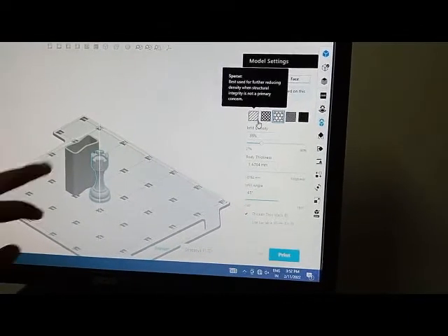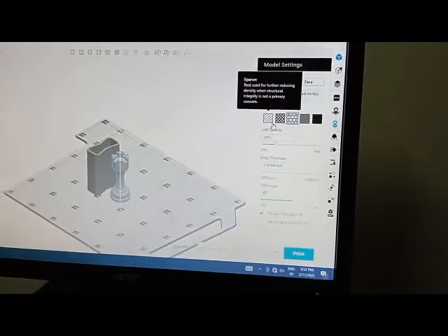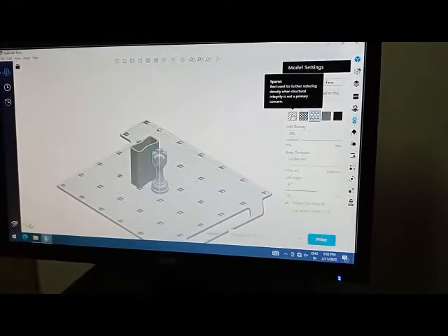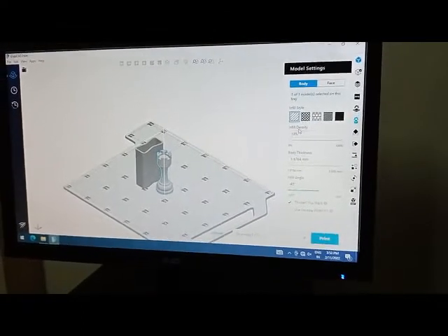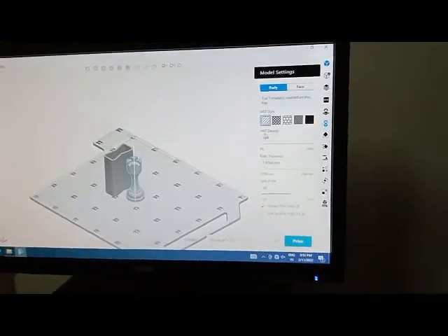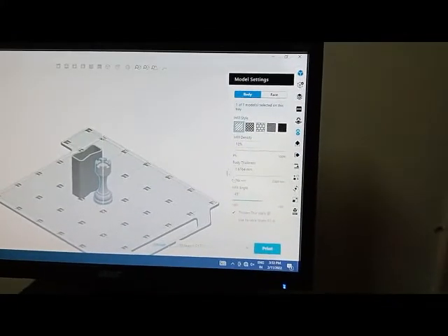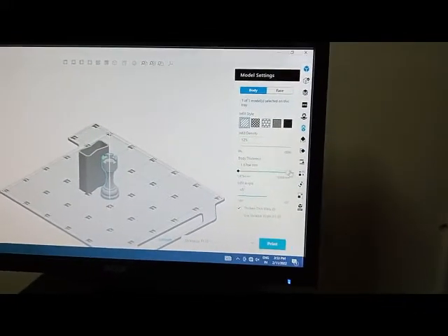Since we are making this chessboard piece, we'll make it in the lowest density. So this is the infill density, basically how much percentage of material is going to fill the part. We also have body thickness, which we can increase or decrease.